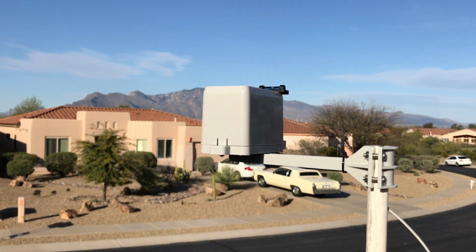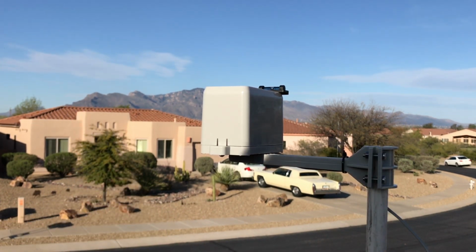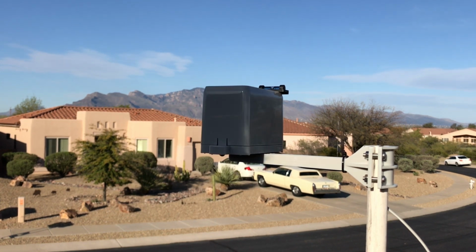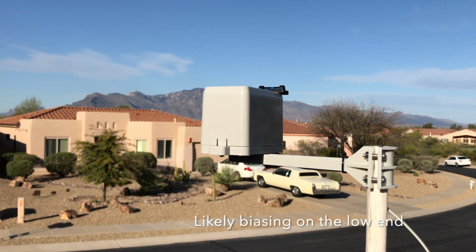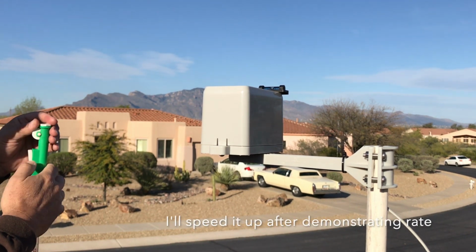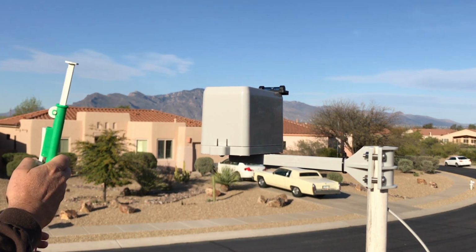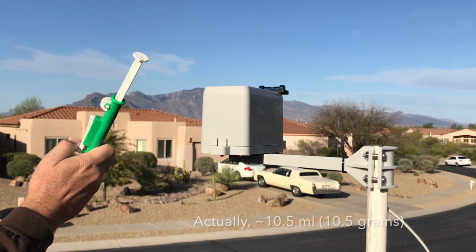Okay, I'm going to try this again, this time using a pipette to control the rate that I'm introducing water into the tipping bucket rain gauge. I have a feeling that I'm overwhelming the bucket, and that might be having an impact on my results. So here goes. This is going to take a little while. Each one of these is going to be about 11 milliliters.